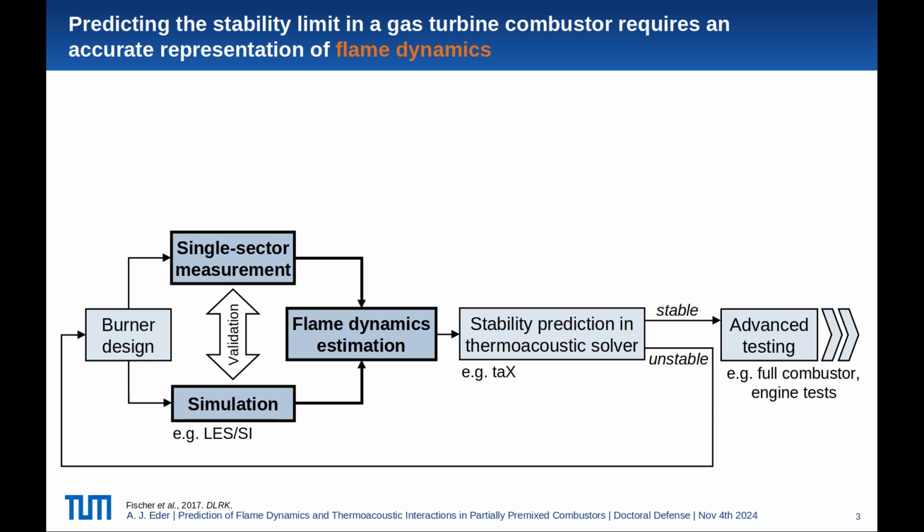Another problem is that the earliest indications of thermoacoustic combustion instability often occur during full combustor or engine testing, and these are typically in the late phase of a development program. Therefore, a thermoacoustic design process for aero engine burners has been proposed recently to confront this issue. And this process is shown here, which is a two-step strategy.